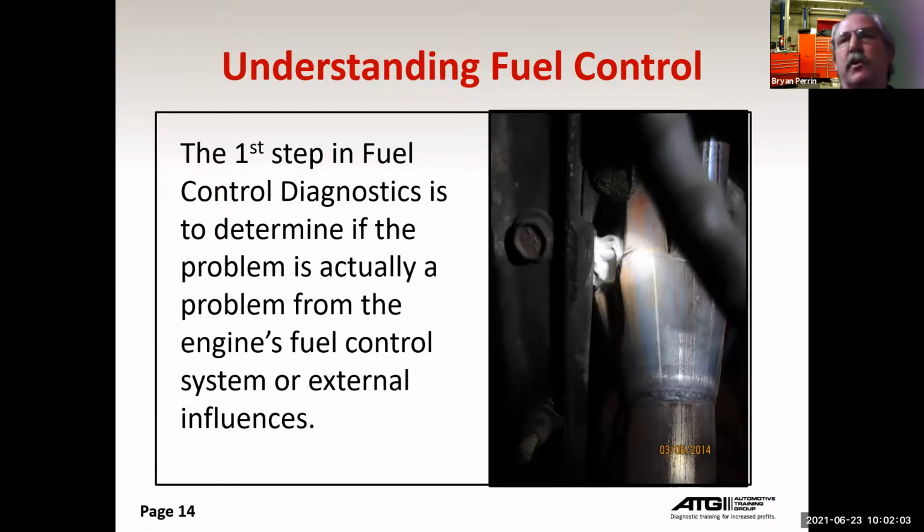They checked it for exhaust leaks. It was failing for high NOx. Lambda said it's running lean. The catalytic converter wasn't working right. Lambda really wasn't off that much. But I don't care what the other shop says, I'm testing it. So I injected smoke using a smoke machine into the exhaust system by removing the O2 sensor,